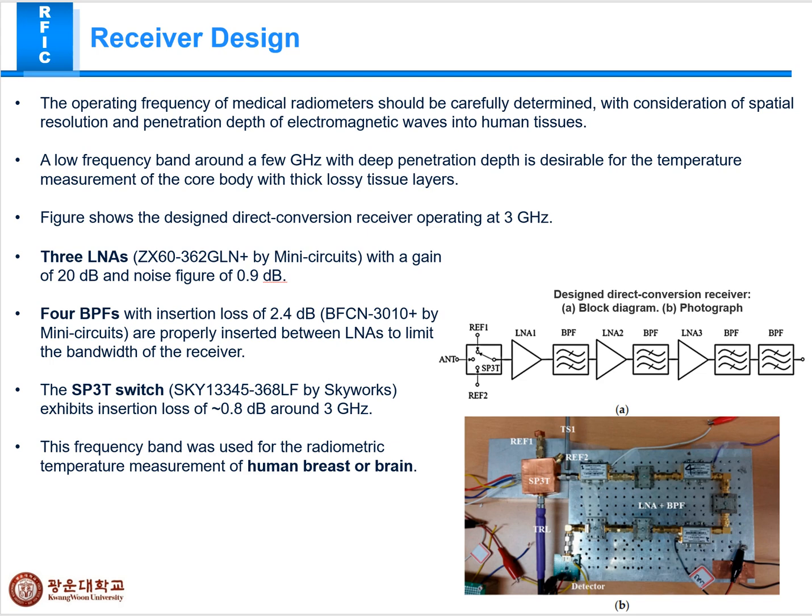The BPF model was BFCN-3010 from Mini-Circuits, inserted between the LNAs to limit the bandwidth of the receiver.